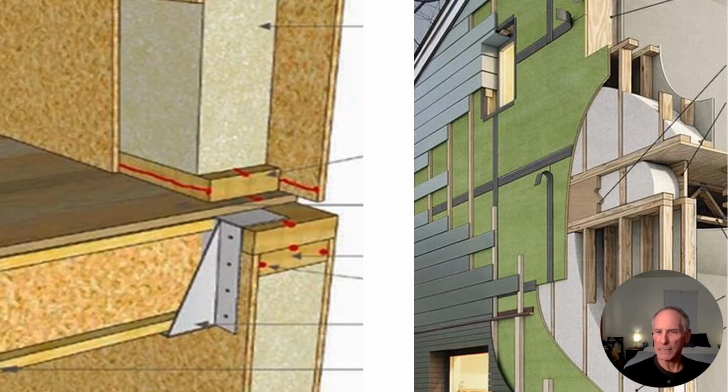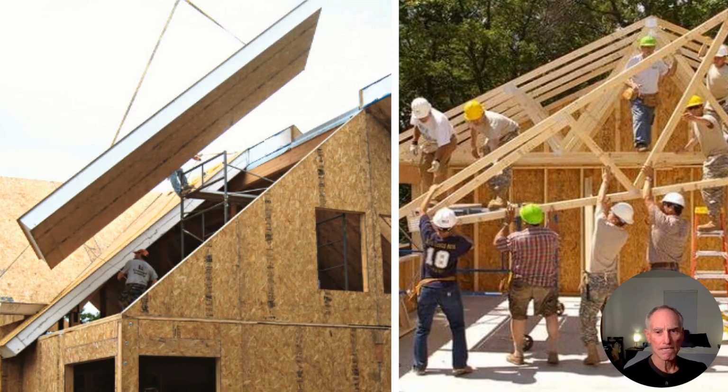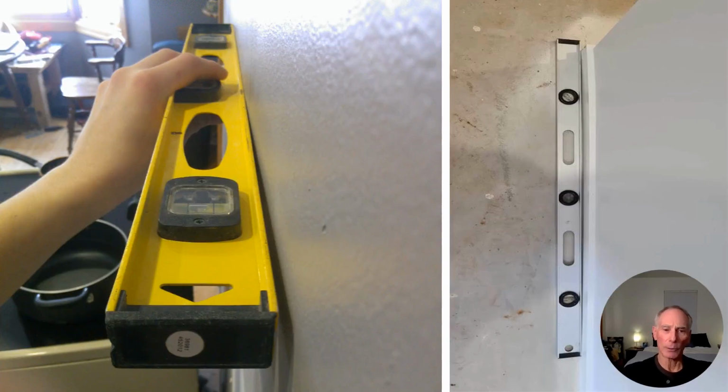And then when we look at the detail of the assemblies, you see it firsthand. On the SIP home on the left, and an equivalent continuous insulation assembly home on the right, you see again, you don't have to manage all the framing details, the in-place insulation that's done in the field, the rigid insulation that's put outboard, all the control factors that go along with that, they all go away. Then next, you can look at just the field construction process itself, just how simply panels assemble versus constructing wood framing in the field.